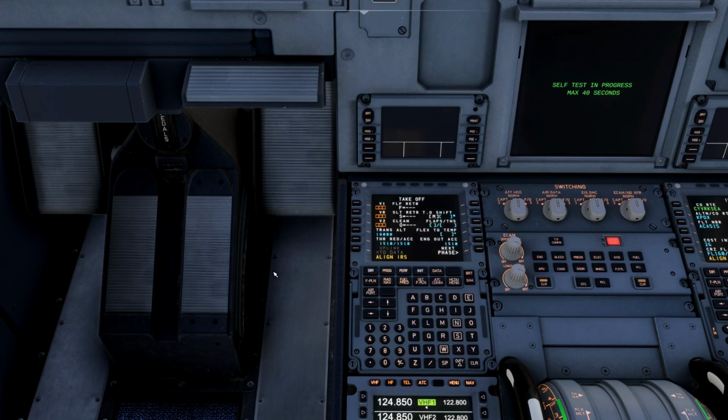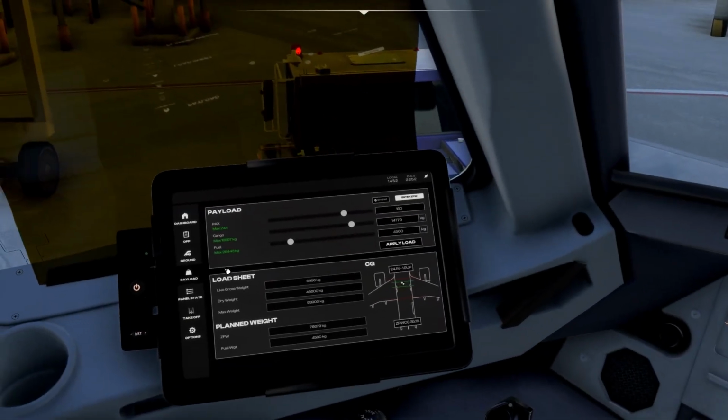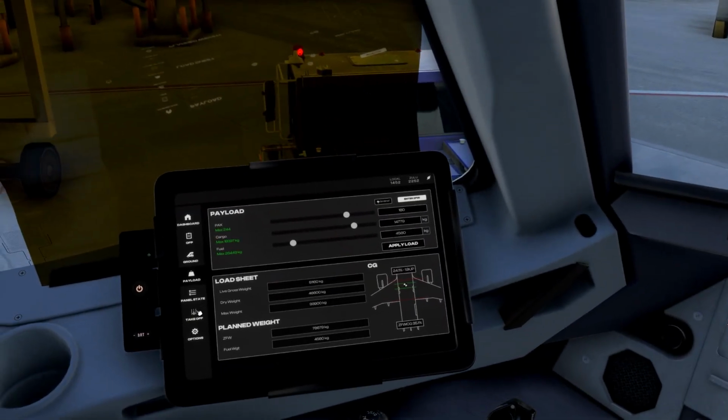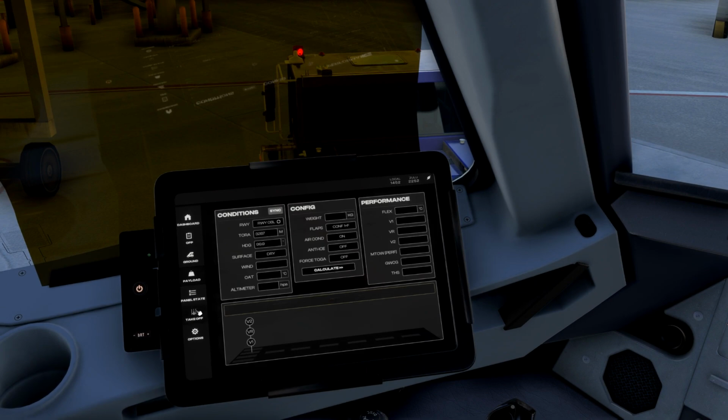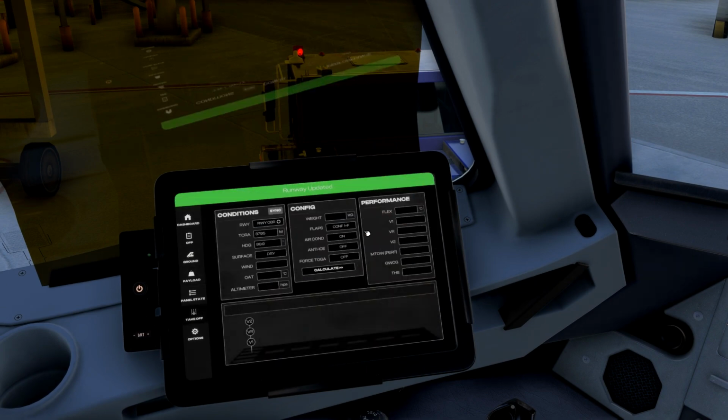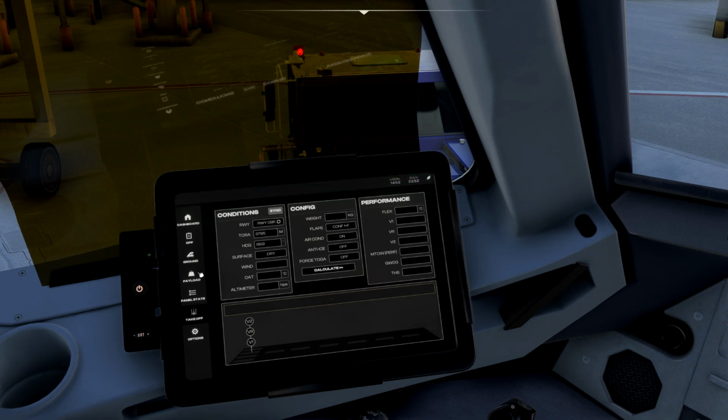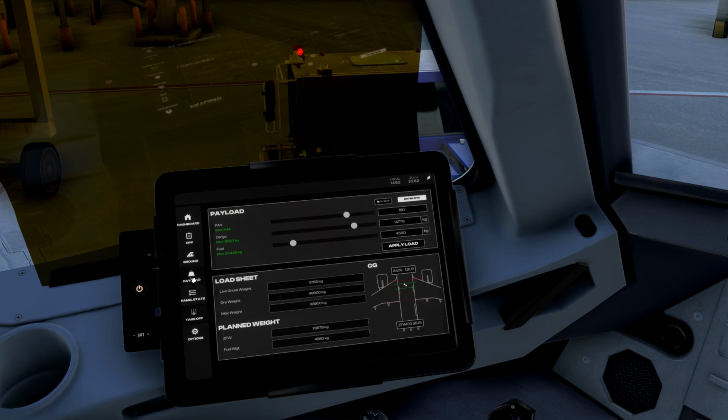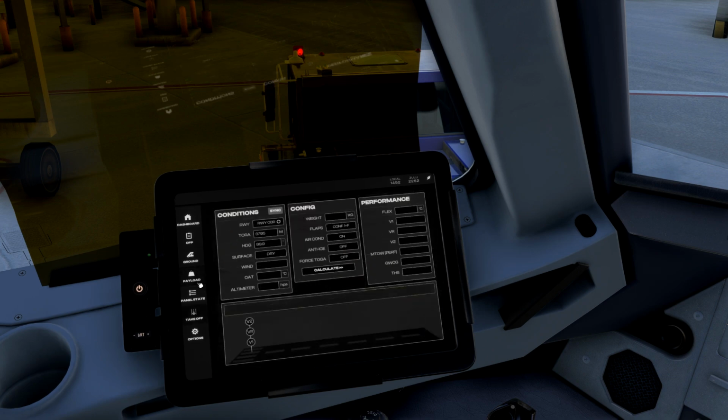Also, the information that we synced in our... We didn't sync it yet. That's why we're back here at the flight board. Make sure the runway is correct. 8R, 8 right. Add the weight. We need that weight. Pull that weight, ZFW, from the payload screen here. There it is. Right, ZFW. And we're going to add that.